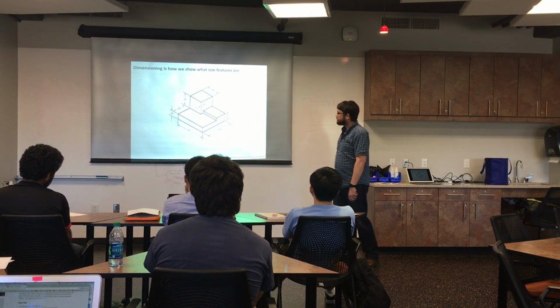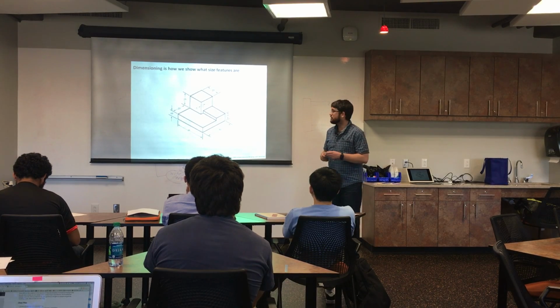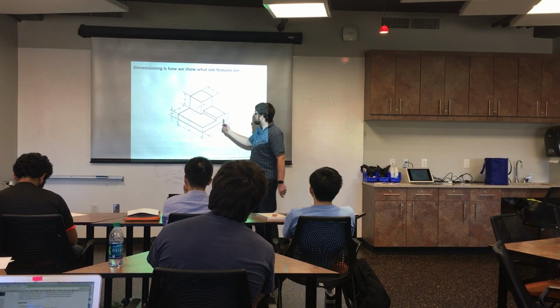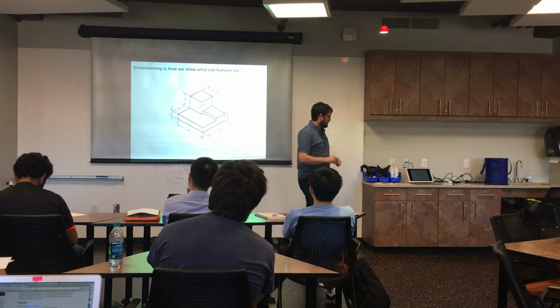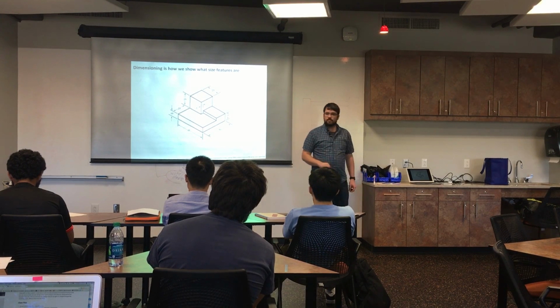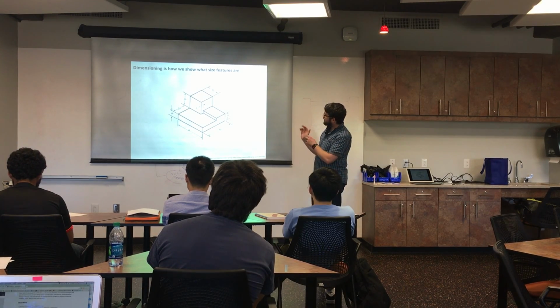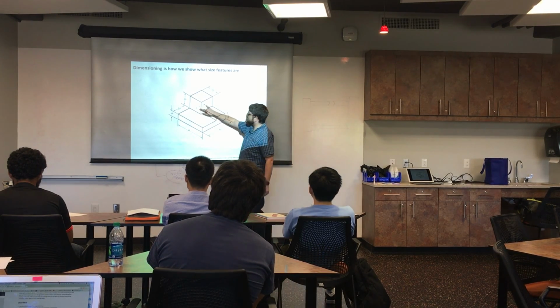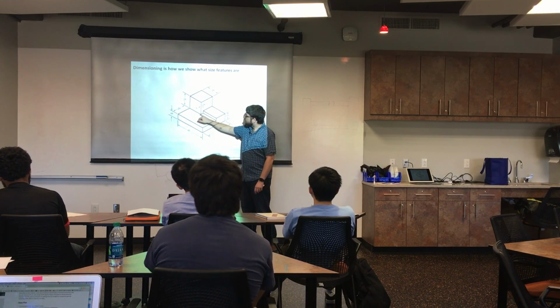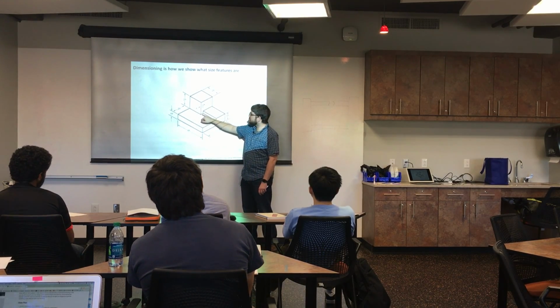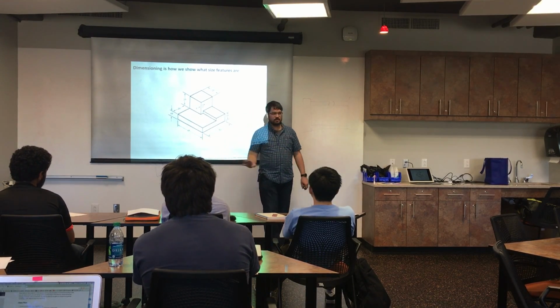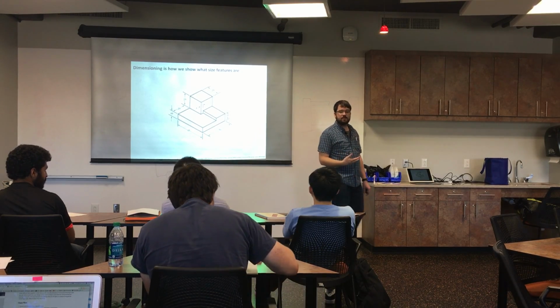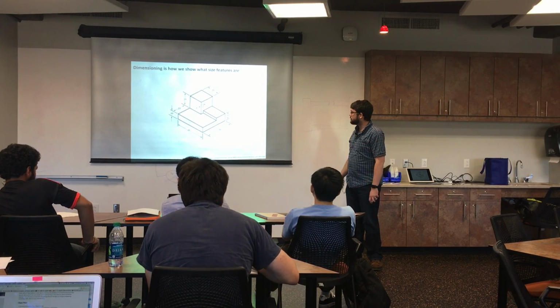All right, now on to dimensioning. This is the dimensioned isometric view of that part that we looked at in the beginning. And you can sort of figure out where everything is by looking at it in 3D. Okay, what's this? Okay, so that's 5 back from the face of this to that. It's not necessarily the easiest thing to look at, though. We generally don't dimension isometric views, just the 2D views.